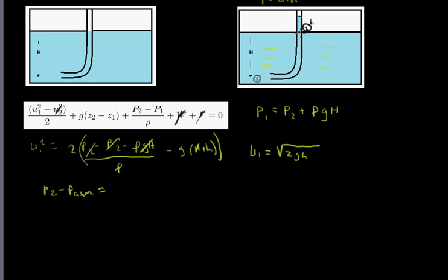So normally if we were doing a manometer problem, we would say that P2 is equal to the pressure right here, which is atmospheric pressure, plus rho g lowercase h. So I subtracted the atmospheric pressure over, so we know that this is going to be rho g lowercase h. So we have that information on hand. And then P1 is going to be the same thing. P1 again is going to equal our atmospheric pressure, so PATM, plus rho g capital H.